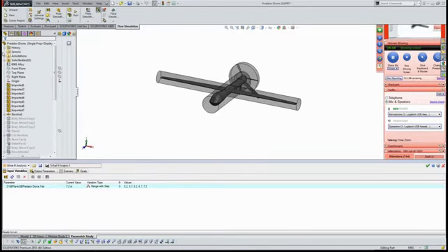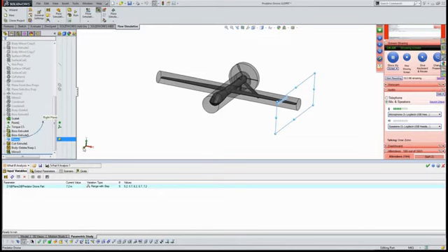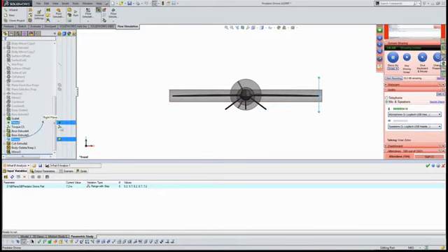Now, this particular what-if analysis, because this is an imported body, I had to do a little bit of gymnastics here. What I did is I created a plane. And I basically am offsetting that plane different values to bring it in, 5.2 meters, 5.7, 6.2, 6.7, and 7.2 meters.